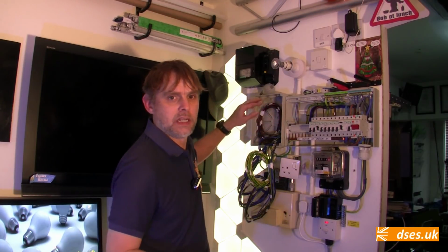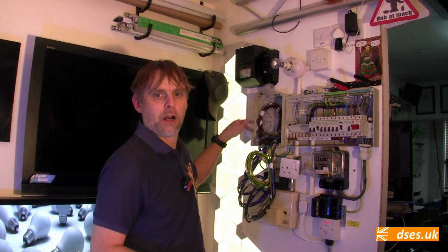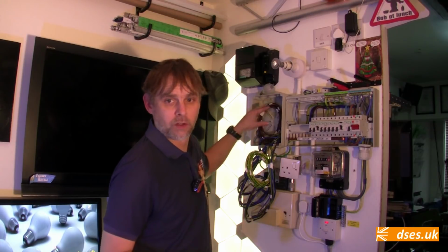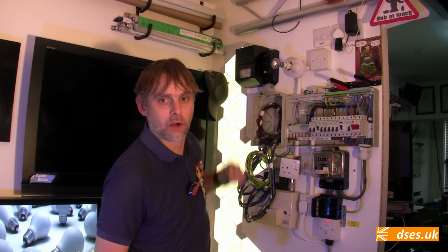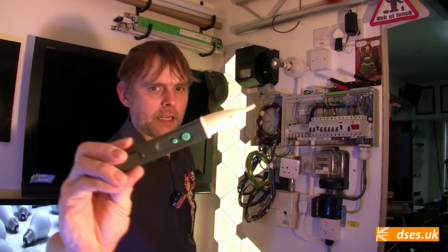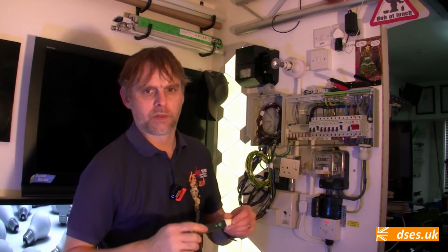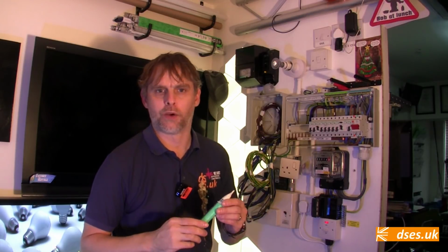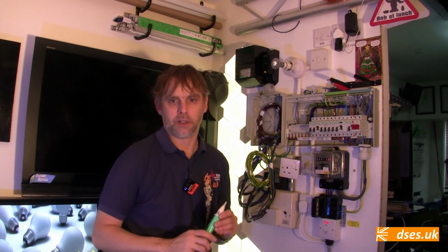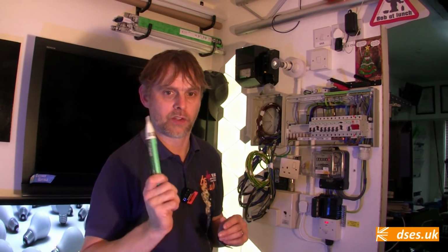That said, we know the socket wire is energised as we can see it physically switched on here. There's 230 volts AC on this socket's 2.5mm brown wire looped here, although not on the 1.5mm lighting wire taped to it, as the breaker for that circuit is off. I can show that the socket wire is energised with this, a non-contact voltage indicator. These come in many forms, this one being a Q-Tech Q-Stick Duo with a rather pleasing two-tone toot, although a Fluke Volt Alert is the one I personally tend to tote on the tool belt.